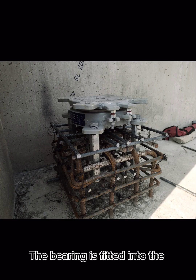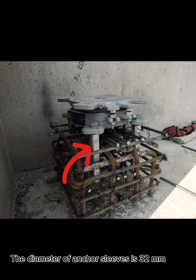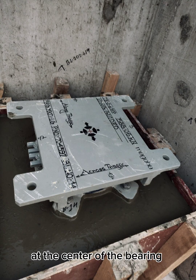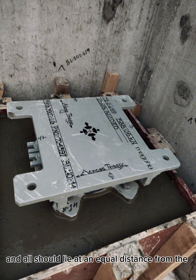The bearing is fitted into the reinforcement cage with help of anchor sleeves. The diameter of anchor sleeves is 32 millimeters. The bearing is designed in such a way that the concentric loading gets applied at the center of the bearing. All four of the bearings should lie at the center line of one another, and all should lie at an equal distance from the dirt wall.